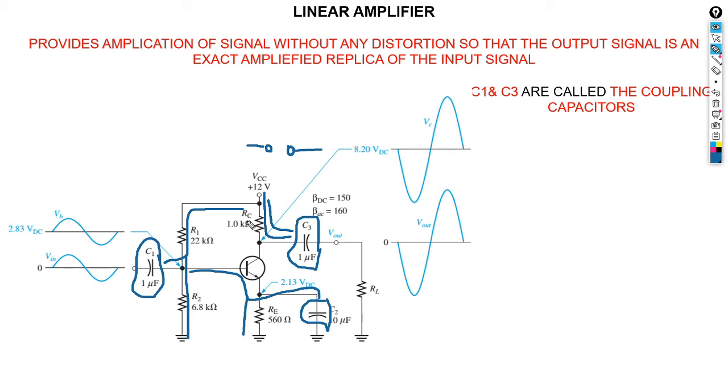Can you see? But now look what happens. If you come with an AC current, which is our signal, this current will flow through those capacitors, because those capacitors behave like a closed switch when there is an AC current. Can you see? And here it's going to be the same. The purpose of these capacitors in our circuit is to make sure that when we combine an AC source and a DC source, the two currents don't mix with each other. Can you see? What we want to amplify is an AC signal, because with AC we know that we're going to have a sine wave.